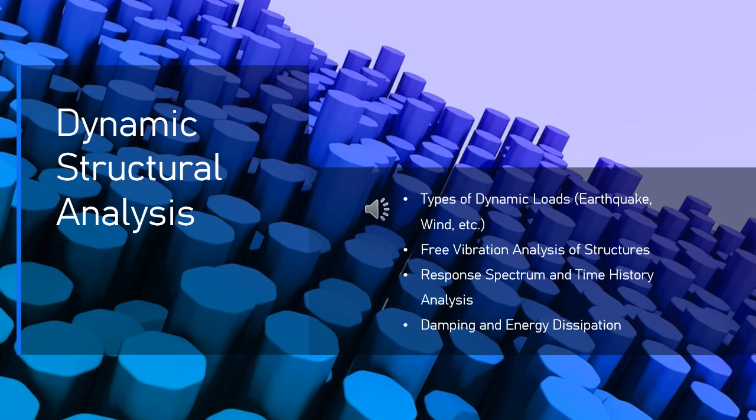Types of damping systems. 1. Viscoelastic dampers. These dampers absorb energy through the deformation of viscoelastic materials. They are often used in tall buildings, bridges, and other structures subject to seismic or wind forces. 2. Tuned mass dampers, TMD. A tuned mass damper consists of a large mass mounted on a spring and damper system. It is typically used in high-rise buildings or towers to reduce wind-induced vibrations or sway.